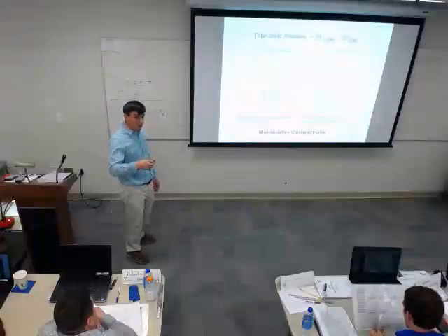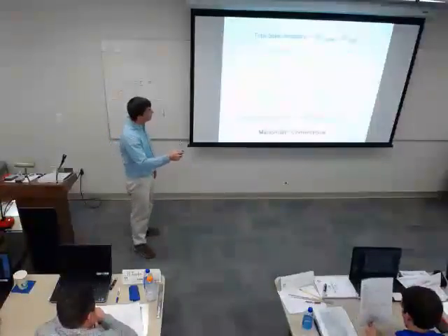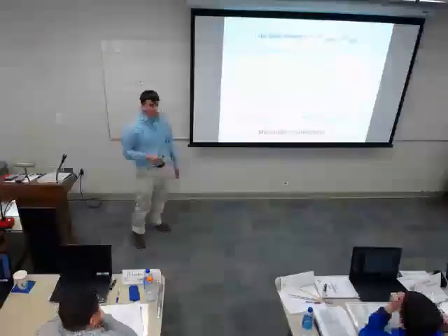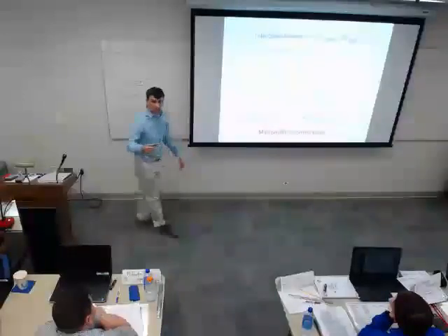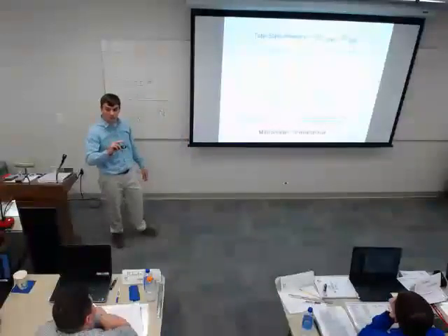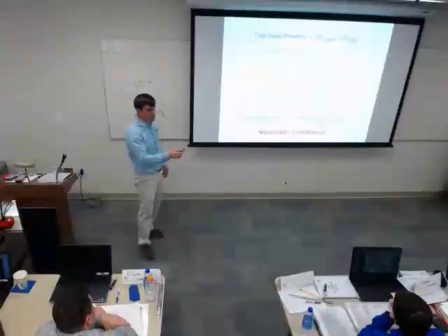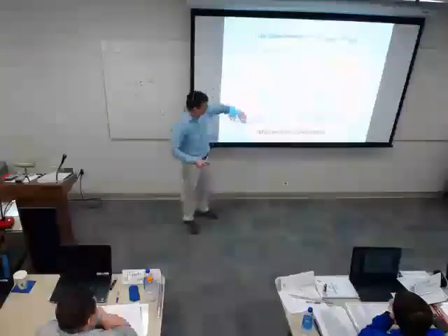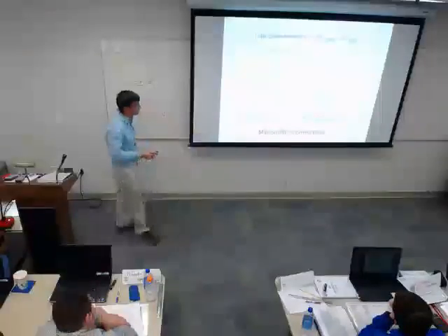Okay, like I said, that was for a positive pressure situation. If I'm on the suction side of my fan, this is going to be a negative pressure. You're going to want to hook that up to the low side now, because if I hooked up to the high side, it would actually suck the fluid out of it. So you've got to pay attention to which pressures are negative or positive. Does that make sense? I'm negative of the atmosphere. The atmosphere is actually going to push the water back up, and you don't have enough room. You would actually lose fluid potentially if you hook up on the wrong side.